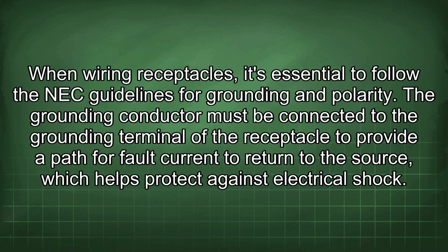When wiring receptacles, it's essential to follow the NEC guidelines for grounding and polarity. The grounding conductor must be connected to the grounding terminal of the receptacle to provide a path for fault current to return to the source, which helps protect against electrical shock.